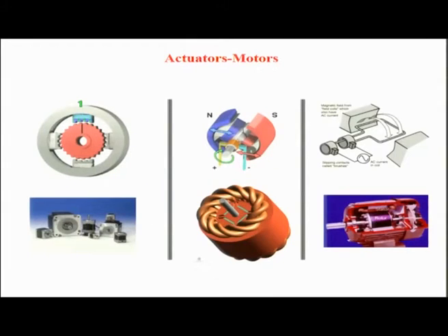Taken together, the sensors, actuators, controllers and power supply form the basic elements of any control system. If you look discretely at what these actuators do, this is a motor where the magnetic field is being varied between different places, from 1, 2, 3 and 4. So there is a rotating magnetic field on the stator which makes the rotor move, which gives you rotary power out of the system. These are some of the systems I'm mentioning. Again, there can be a DC signal given to the central shaft, and a stator which is more fixed in nature with north and south poles, which could cause circular motion to happen.